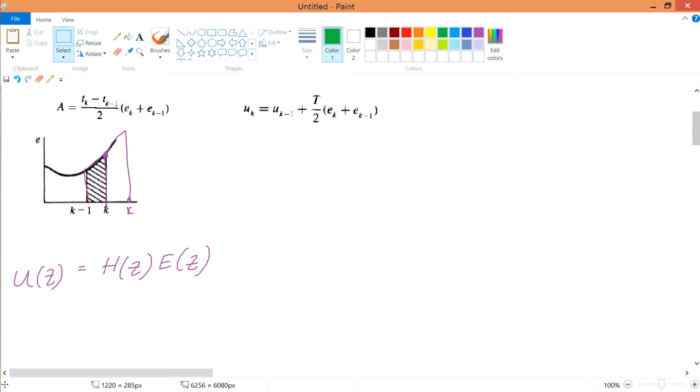In this video, we'll talk about trapezoidal integration into a transfer function. Later on you'll know what I mean. If you still remember, we have a trapezoidal integration over here, and we say that if you input a certain piece of information with the previous information, divided by 2, you have the next output coming out over here, so you reflect your particular next output. After which you input another 2 values, divide by 2, and get another output. Then you have k plus 2 now, this is k plus 1, and you reflect again using k plus 1 and k plus 2, and go on and on.